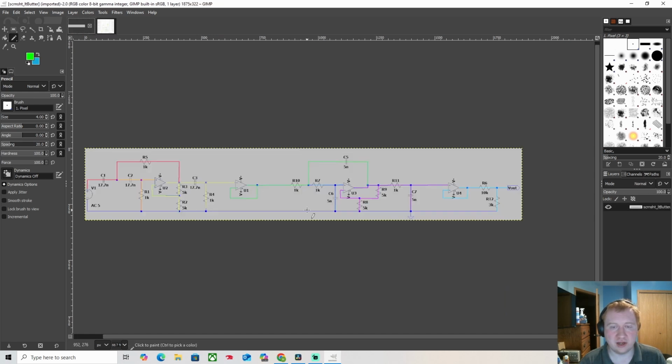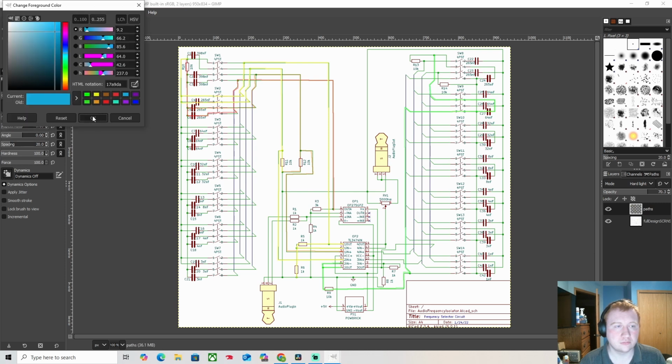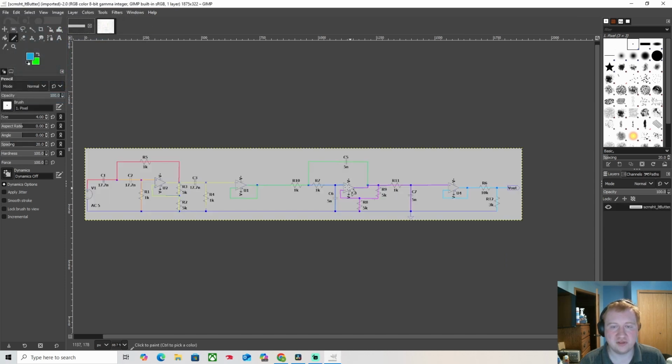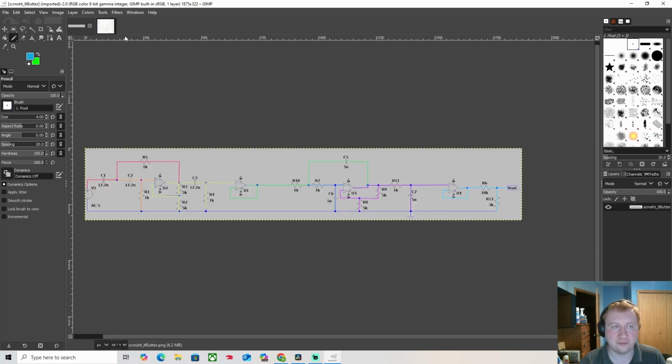So the next color here is the blue. Which comes off the first node here, which would be here. And in this case it goes up through the resistor. Does not want to go this way because that's open. So it needs to come down through the bus and through the switch to ground. And we also need it to route down to the positive side of the op amp on that side, which is what we see right there.